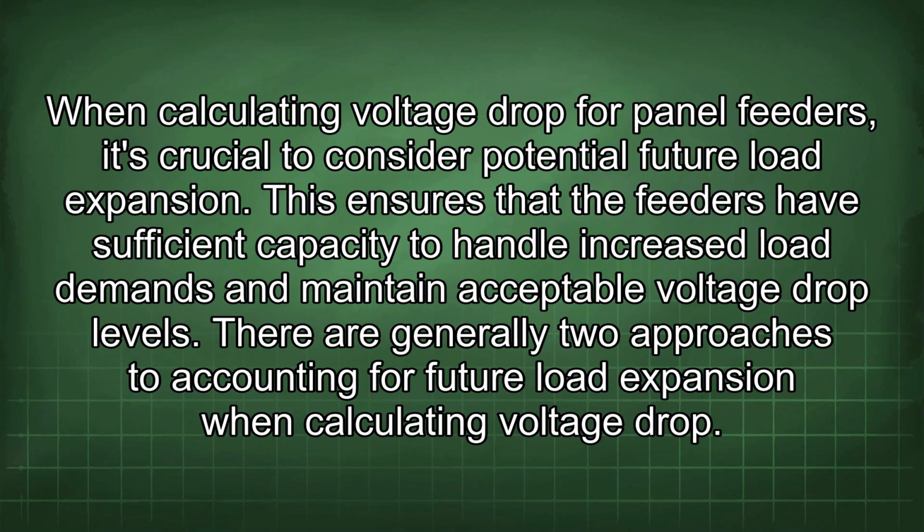When calculating voltage drop for panel feeders, it's crucial to consider potential future load expansion. This ensures that the feeders have sufficient capacity to handle increased load demands and maintain acceptable voltage drop levels. There are generally two approaches to accounting for future load expansion when calculating voltage drop.